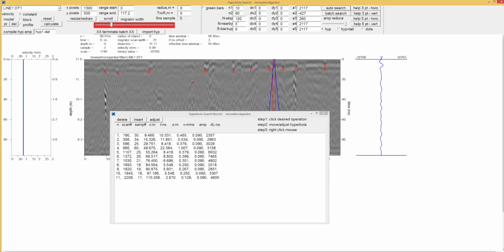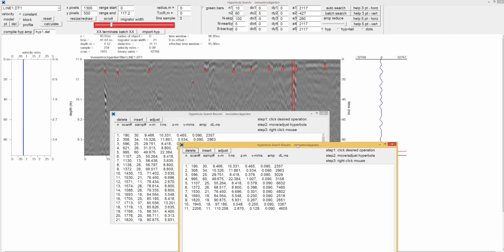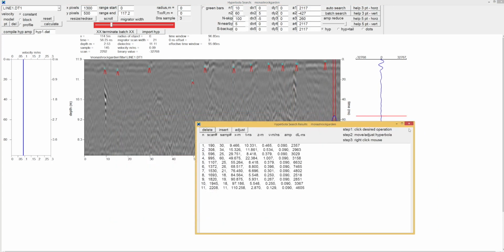You need to figure out some balance, and most concrete, I should say the rebar in concrete is laid down in a mesh usually. What that means is that your reflectors in your radar data are going to be pretty much constant at the same depth. They're going to be more or less the same width and that sort of thing as well.